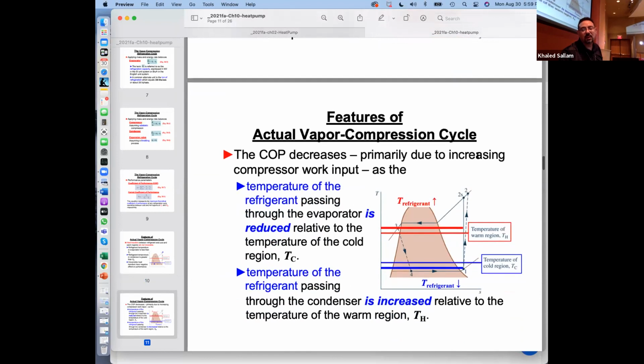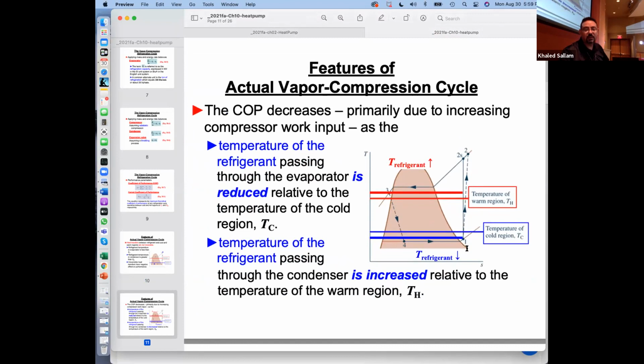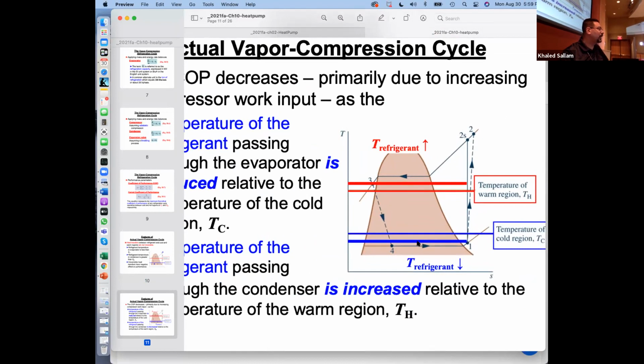Good. So now, why do you have to convince your family not to set the thermostat really low in the summer? Because when they say, Daddy, we want it to be at 70 rather than 75, the refrigerant needs to go even lower, right? And that will make the compressor go a really long way, especially if the temperature is not 80, the temperature is 90.